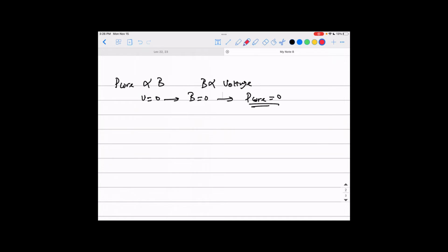Okay? So again, back to the power. You know that P no load equals 3 I no load square R1 plus the P friction and windage plus the core losses. And the core losses here equal 3 E2 as a magnitude square over RC. Okay, guys?